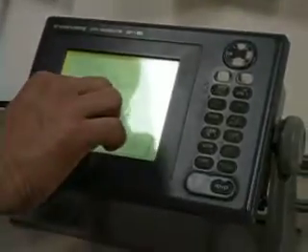But when you go to the ship now, most of the charts are under WGS 84, World Geodetic System 1984 datum. So it is better to always keep WGS 84, and even if you don't put the correction for a big chart, the correction of 0.1 minute is a pencil tip. So for a ship, 1 meter, 10 meter, because 200 meter length, 32 meter wide, a little bit of pencil distance, no problem. But when you go inside the port, buoyed channel, under the bridge, that time it needs to be very accurate. But otherwise, in open sea it doesn't matter.